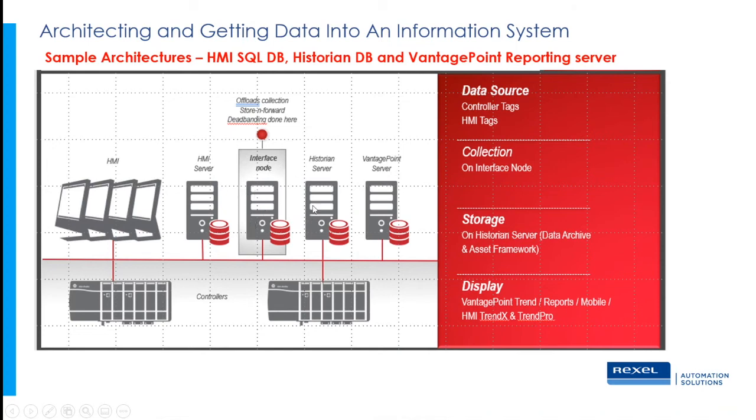Historian has a few different architectures, 3 or 4, one being redundant. One of the things you can add with Historian is what's called an interface node. Obviously PC servers act up once in a while, right? Say you have to take your Historian server down; if you're logging regulatory data, you can't lose that data, right?